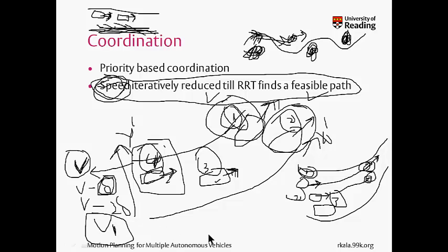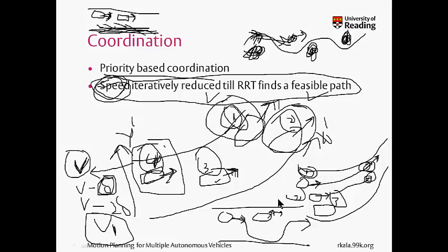Now with respect to the other works that I'm presenting as videos, there are two important points to note. Firstly, this coordination is non-cooperative. That means if a vehicle behind is trying to overtake a vehicle in front, this vehicle will not go towards the side to make the overtake simpler. The vehicle will actually have to go by a very odd trajectory. Coordination is non-cooperative. There are variations possible by which we embed some simple kind of heuristics in order to make the travel plan cooperative, where this vehicle is asked to weave towards one side. But in the current version, we haven't really done that.